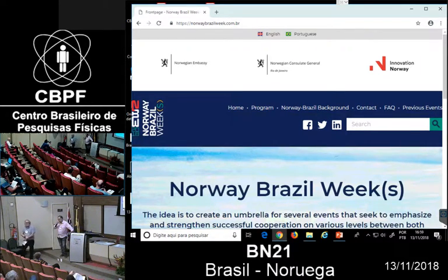Well, I'm not much aware of the methods you're using in Norway, but the focus now on the development of new fields in Brazil is mainly in the pre-salt. And for the pre-salt, the main focus is using CO2 for EOR processes. Petrobras is doing WAG in Lula field because they don't have gas pipelines yet to export the gas production, which is very high.